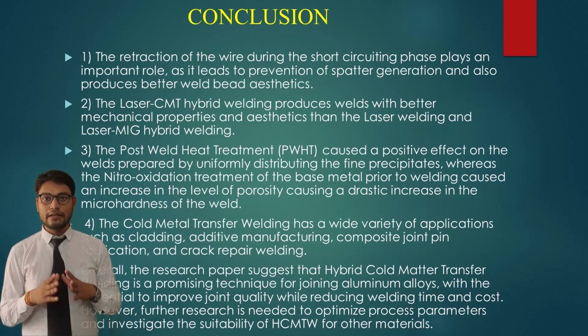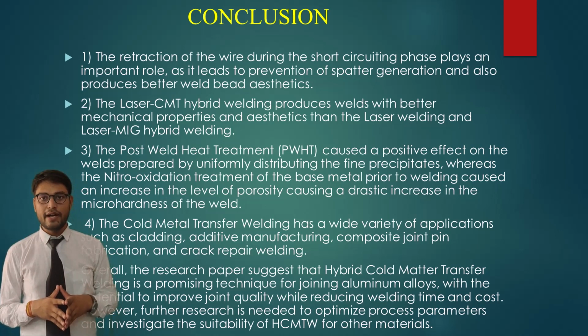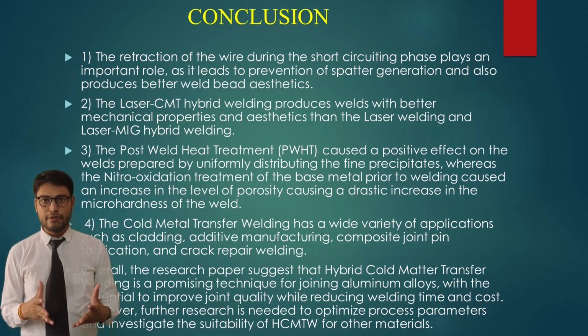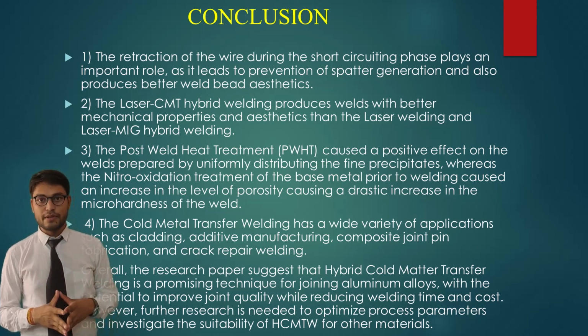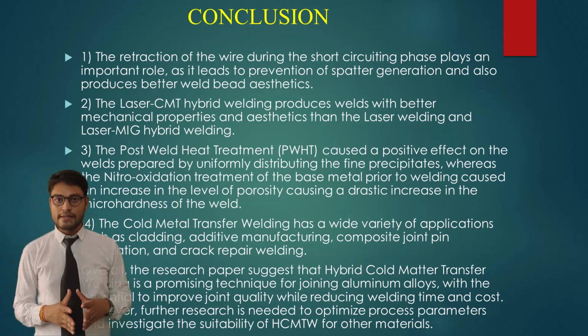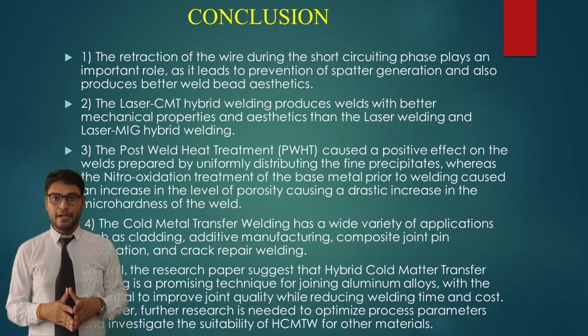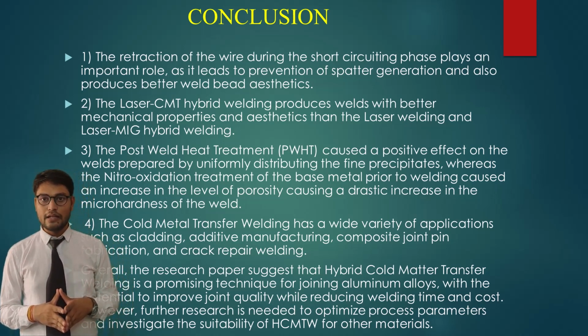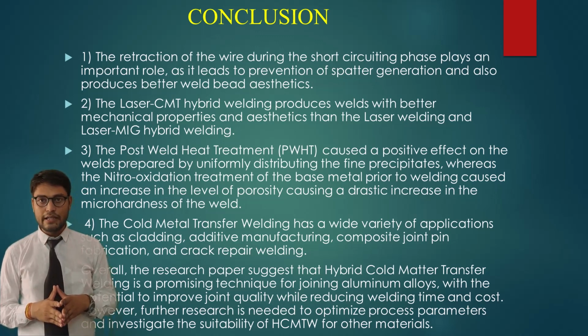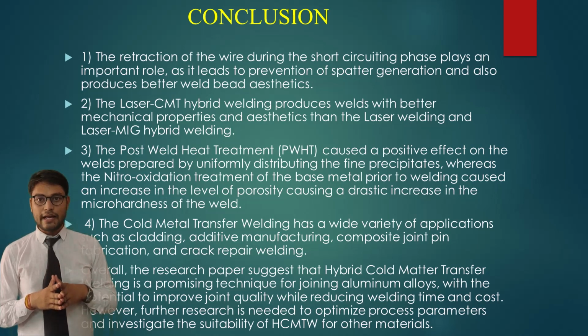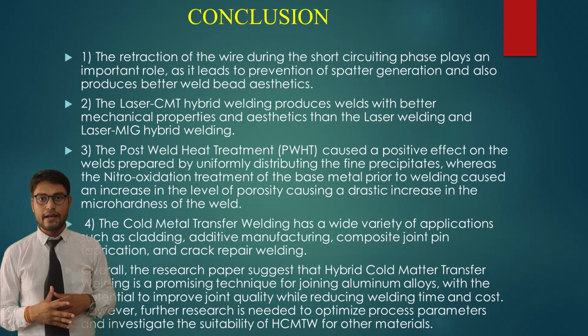And finally, cold metal transfer welding has a wide variety of applications such as cladding, additive manufacturing, composite joint fabrication, and crack repair welding, etc. So overall we can say this seminar suggests that hybrid cold metal transfer welding is a promising technique for joining aluminum alloys with the potential to improve joint quality while reducing welding time and cost. However, further research is needed to optimize process parameters and investigate the suitability of SCMTW for other materials.